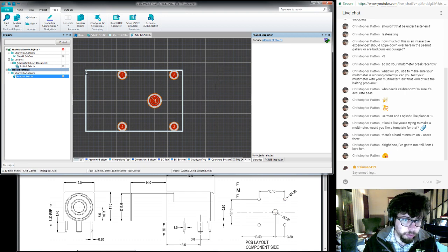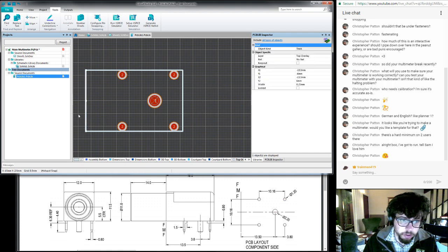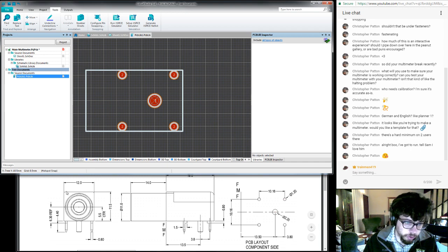And then the other thing I will use during layout is this edge here. Since this is the edge of the flat part, I'll align this up with the edge of my PCB so that then the rest of the jack can stick through a hole in the chassis.